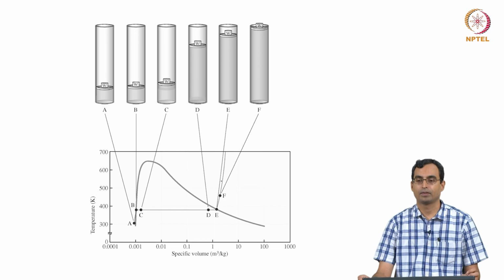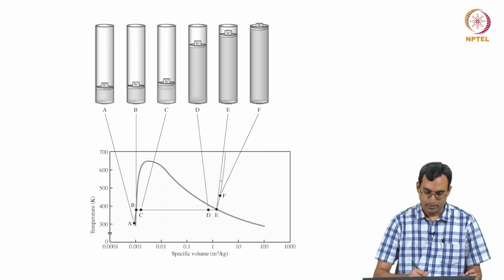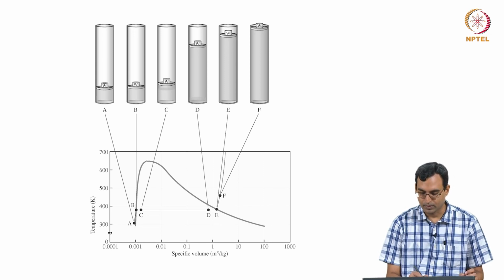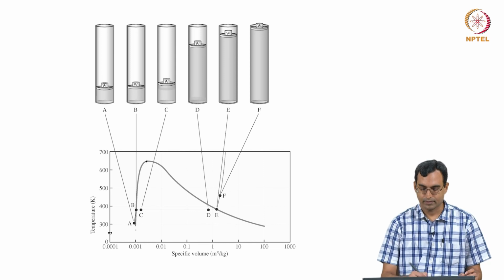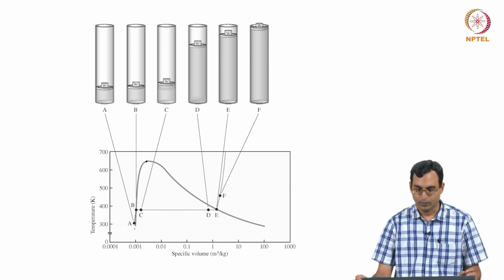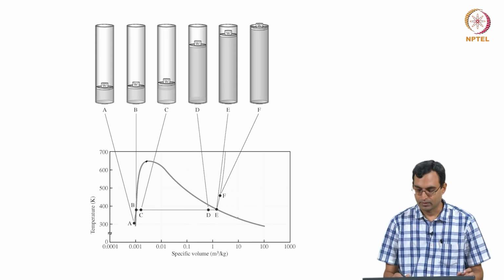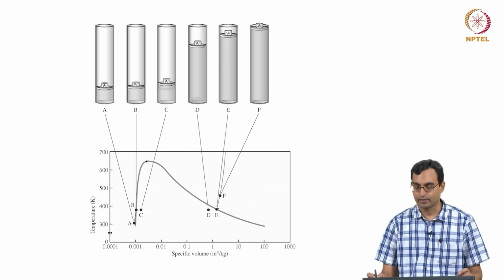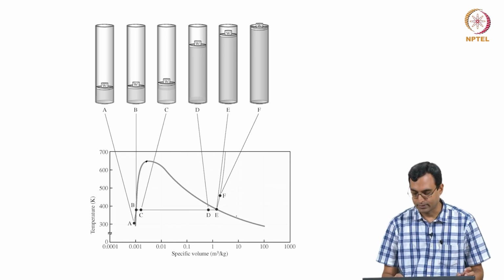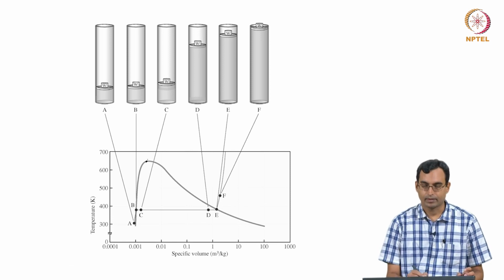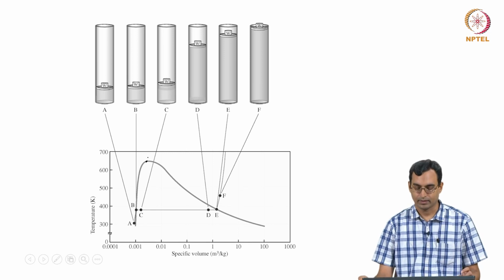So, this is essentially what we looked at yesterday, and we saw that this curve along this point up to the top of it, which is what we call as a critical point, represents the boiling point for liquid to become vapor, and it represents the liquid at the boiling point. So, we called it the liquid line. This curve on this side from the critical point onwards towards this side represents the vapor at the boiling point. So, we call that as the vapor line. We call this as the liquid vapor dome. The top is the critical point where the latent heat of vaporization is 0.